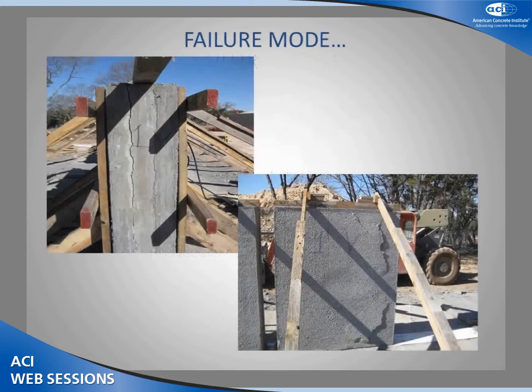So this crack was an indication of a separation of the diaphragm from the poured wall at the 7,000 psi pressure at failure. And as you can see, when the diaphragm started yielding and pulling, it popped shotcrete out. And again, that is not going to happen in a real life situation.